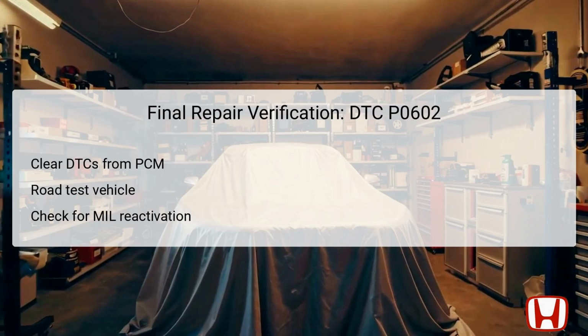To confirm that the repairs have been successful regarding DTC P0602, the next step is to clear the stored DTCs from the PCM. After erasing the codes, it's essential to conduct a road test to evaluate the vehicle's performance under real-world conditions. During this test drive, monitor various functions to ensure that the PCM is effectively managing engine operations without any hiccups. After completing the road test, check if the malfunction indicator lamp, MIL, reactivates. If it stays off, the repair is considered successful. Additionally, you may rescan the PCM to verify that no persistent or new DTCs emerge. This process serves as a comprehensive method of ensuring that the initial programming error is effectively resolved.